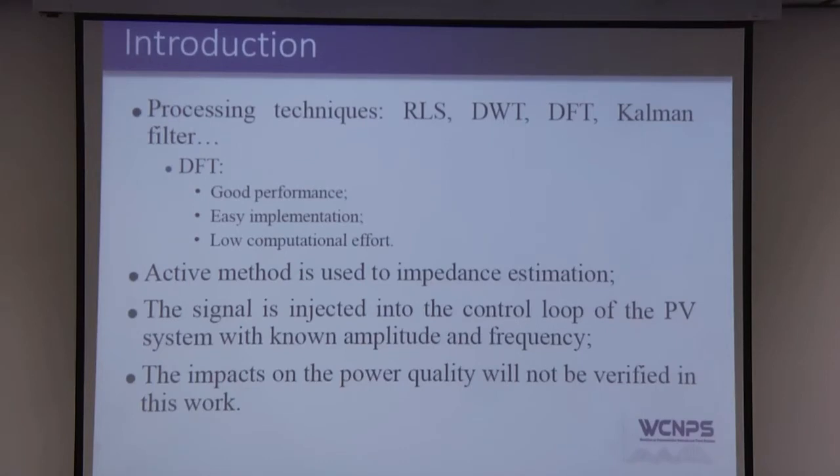In this work, the DFT was used because it is simple to implement and has good performance. It is easy to implement, and it has a low computational effort. Also, an active method was used to estimate the system impedance, in which a current signal was inserted in the current reference of the PV-based system, but the power quality impact will not be verified in this work.